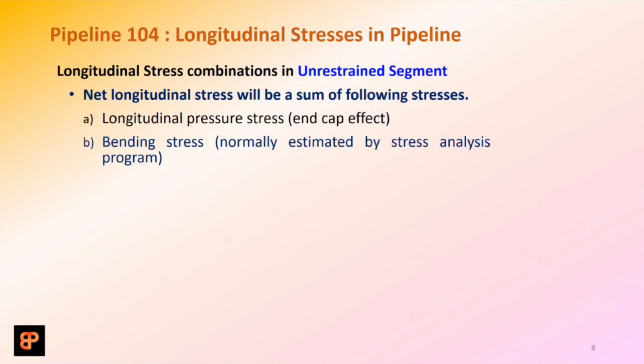There will be bending stress, which is related to the support spans and bends and bending moment acting in this, which is any above ground supported pipe with the support span will encounter these stresses. Normally it's going to be negligible if we are providing adequate support span.